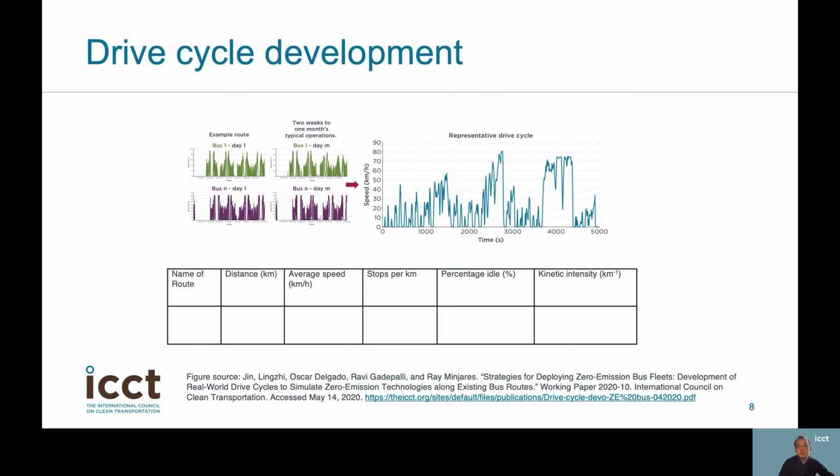The characteristics of bus fleets and routes that are collected in the previous two steps can then be plugged into a computer algorithm to calculate a drive cycle that's based on real-world bus operations data. Buses' operation conditions, from the weather to the speed and terrain, can be different from city to city, route to route, which is why this real-world drive cycle is extremely important. Instead of an arbitrary, generic, and sometimes unrepresentative duty cycle developed in a laboratory, the real-world drive cycle is more representative and truer to real operating conditions of buses and their energy consumption.